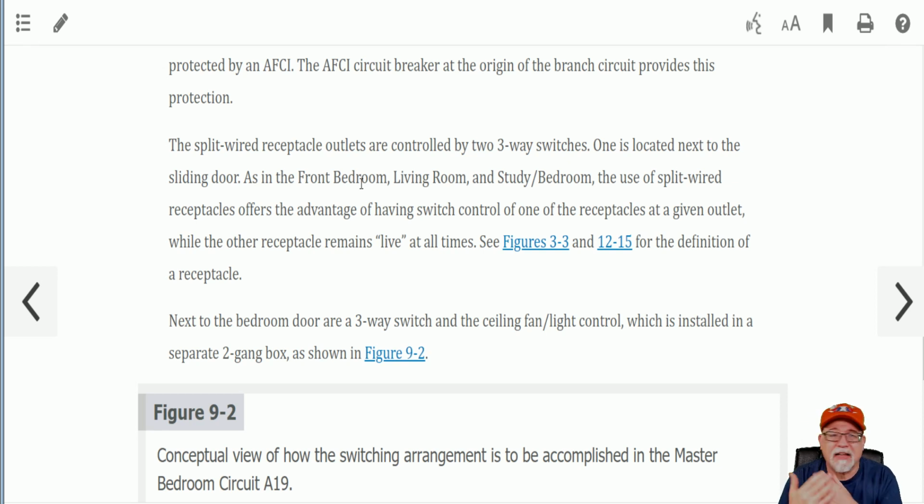Now that's true, and that's why we have overcurrent devices. That's why we have that in place. But if you had to turn the grounds up in that scenario, then if the plate came down, it would just hit the ground pin, and it wouldn't short out. Okay, not a code requirement. Might be a local jurisdictional requirement, an AHJ requirement, because they can supersede the code, but it's not an NEC requirement. It's just general conversation. That's all it is.